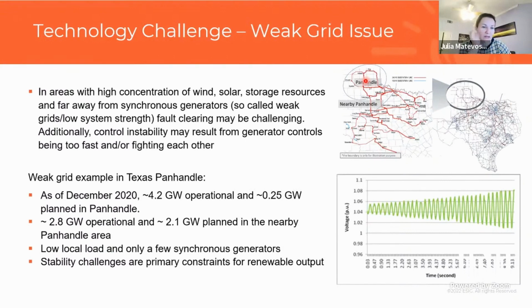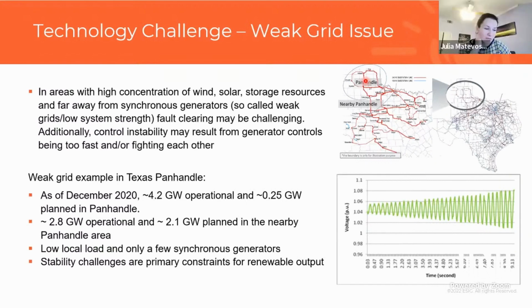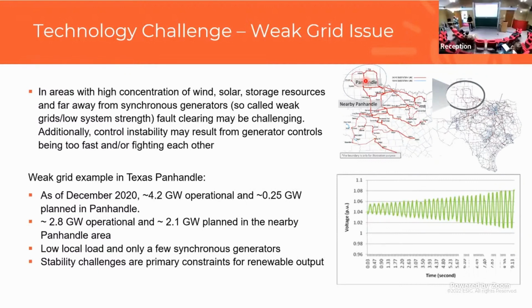And they can isolate it to a group of inverter-based resources in a weak grid area in case of a voltage stability issue. It can be isolated to, say, a plant connected radially with a series compensated line. And that inter-area oscillation between synchronous condenser and synchronous generators that they saw, that was only in a study, but it was also clear what was causing it. So in ERCOT, they haven't experienced yet a case where it's hard to say what's causing it.